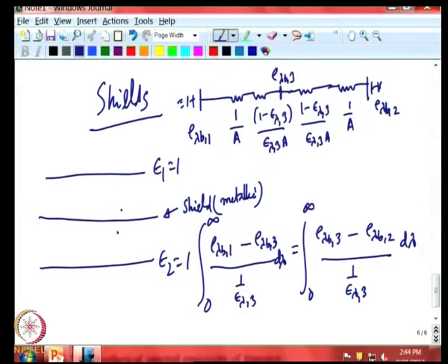So, now we have to ask what is the temperature of the shield T3. So, this surface 3, the shield. Now, the shield temperature has been such that the heat flow from 1 to 3 has to be equal to the heat flow from 3 to 1, because in steady state the thin metal here cannot retain heat. So, whatever heat it gets from surface 1 to 3 has to go into the other side.